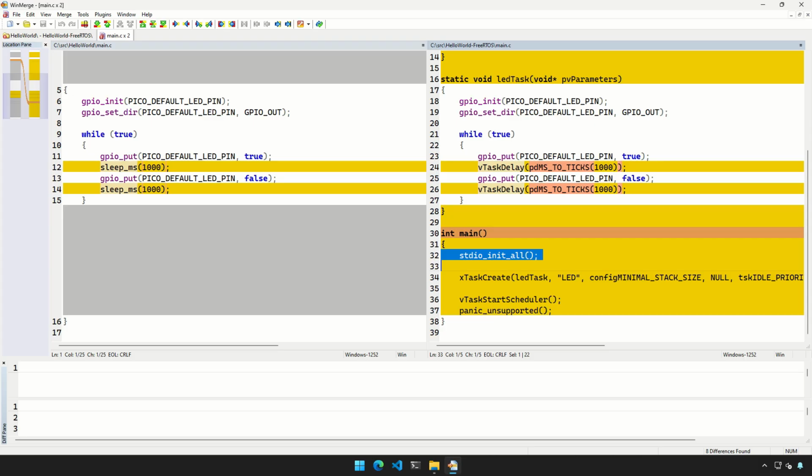That's a usual function call at the beginning of your program for Pico if you want to use the serial port as your printf output, so you can print out anything you want for debugging or looking at what happens in your program to the serial port, which could be connected to your computer, and then you can see on screen what is happening step by step.